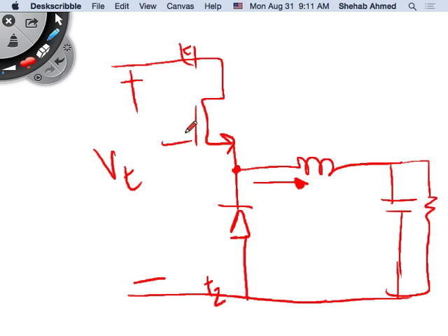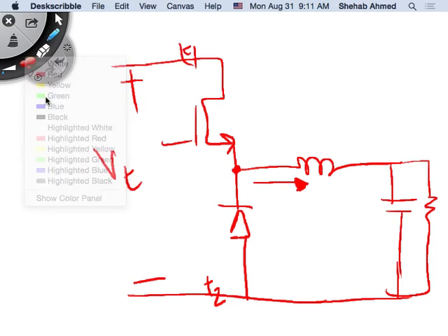We found that the best circuit to put in this case is this configuration of MOSFET and diode, right? We will go back and find the justification, but I will show you a trick. So for this sort of configuration, where my VT is in this polarity and my current is going out into the pole, I use this circuit topology. How about if I want to flip current?